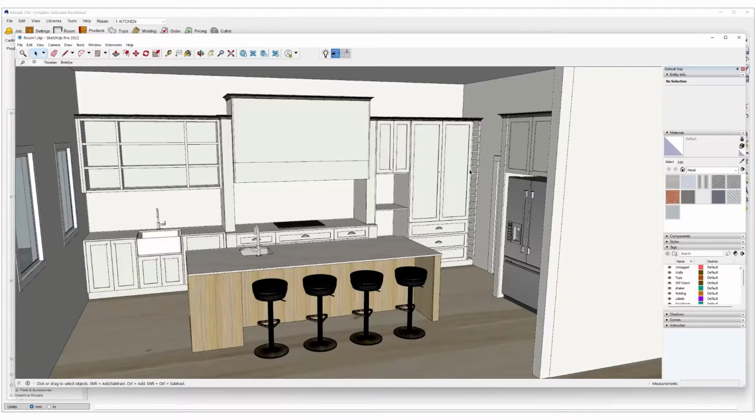So let's get into how we can export out to Spaces. If you've got your VORTEK Spaces extension in SketchUp installed, you'll have this little toolbar at the top of the menu here. You can also get to the same thing by going to Extensions and then down to VORTEK and then the various options here. So we want the Export to VOK option, which you can also do by clicking this option here, Export your model as a VOK file. So I'm going to choose that option there.